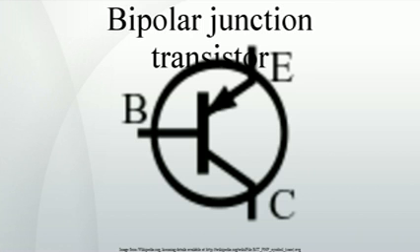In typical operation, the base-emitter junction is forward biased, which means that the p-doped side of the junction is at a more positive potential than the n-doped side, and the base-collector junction is reverse biased. In an NPN transistor, when positive bias is applied to the base-emitter junction, the equilibrium is disturbed between the thermally generated carriers and the repelling electric field of the n-doped emitter depletion region. This allows thermally excited electrons to inject from the emitter into the base region.